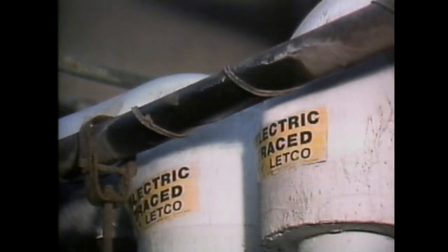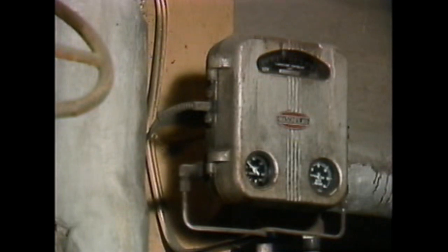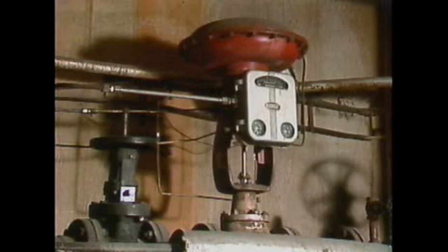If electrical heat tracing is used in your facility, check the heat tracing controls to make sure that all the required heat tracing systems are operating properly. If steam heat tracing is used, check the steam pressure to make sure that steam is available. Then make sure that the steam flow control valve and the steam traps are functioning properly. The general operating checks we've just covered apply to most fluid systems. Your facility's specific procedures will have more details.